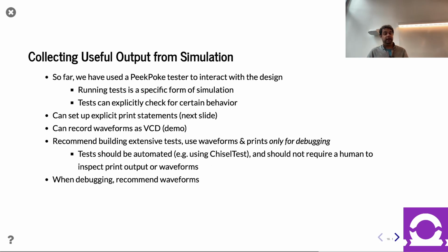Now, every quarter, I am always reluctant to teach people about prints. Sometimes people get too attached to prints. There's a certain point in hardware design where you should abandon prints and use waveforms. For those from the software community who may not be familiar with waveforms, they're actually really amazing. You get the value of all of your signals for all time, right? So there's no need to run it once, realize you need more data, and run it again. No, you just run it once and spend a lot of time looking at the waveform, and in one go you figure out the bug and fix it.